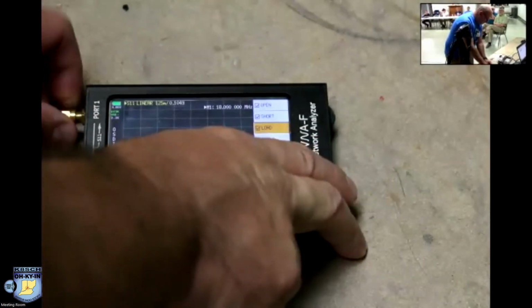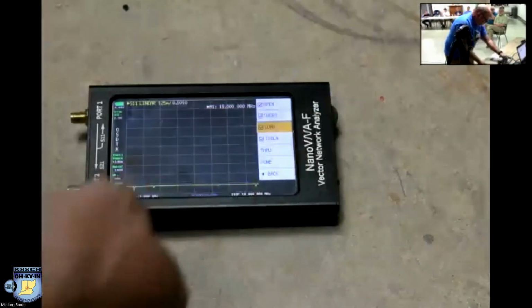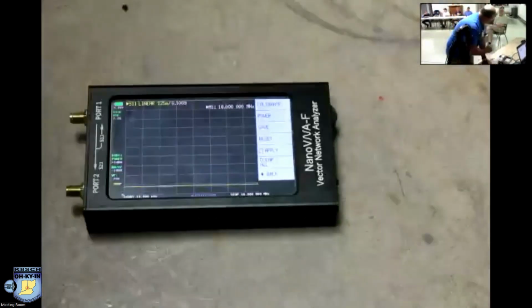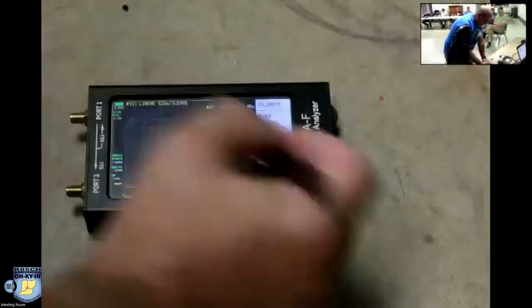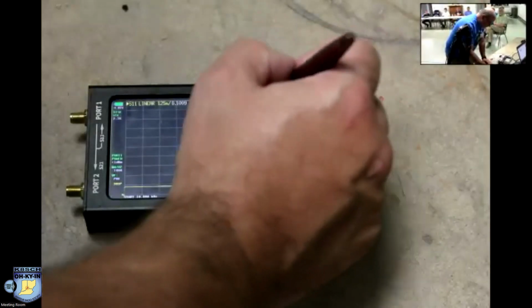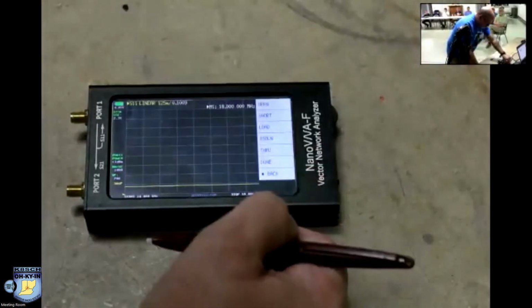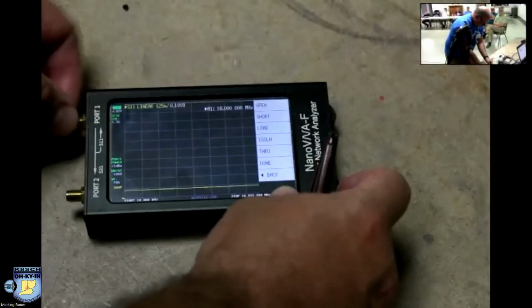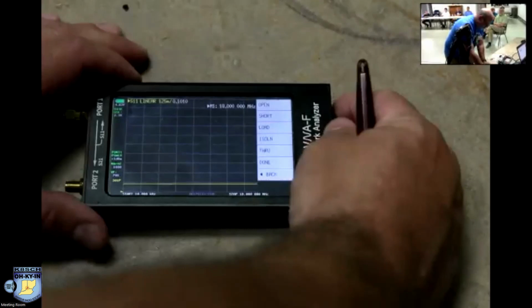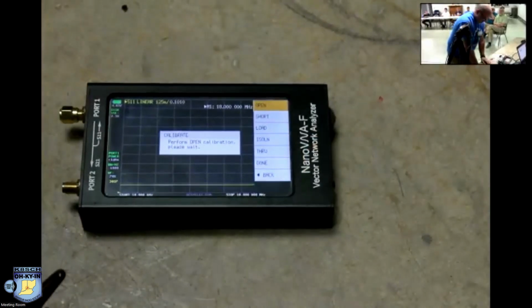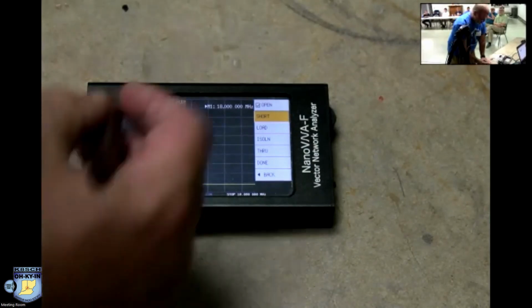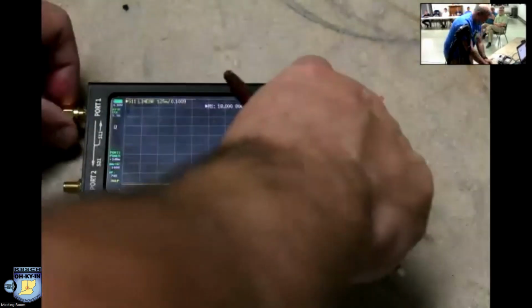It's amazing how much they, oh, shoot, you know what I didn't do? I did a reset. So, as I calibrate to do it correctly this time, you see how in the left column it's empty there? See how there's an O there now? That means it's calibrated for open.